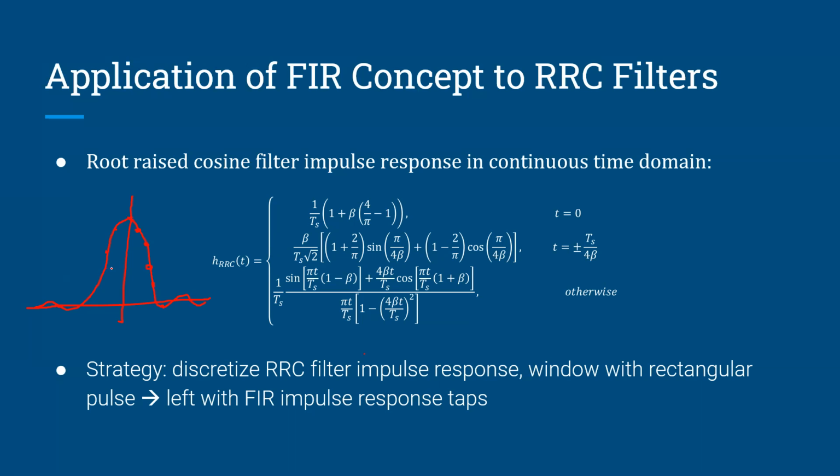You get the point. And then you could turn it into an FIR filter. These guys continue on for infinity, right? You can turn it into an FIR filter by just chopping off the tails and just considering this part here as your filter. And so that would be an example of using a rectangular window as your windowing operation.